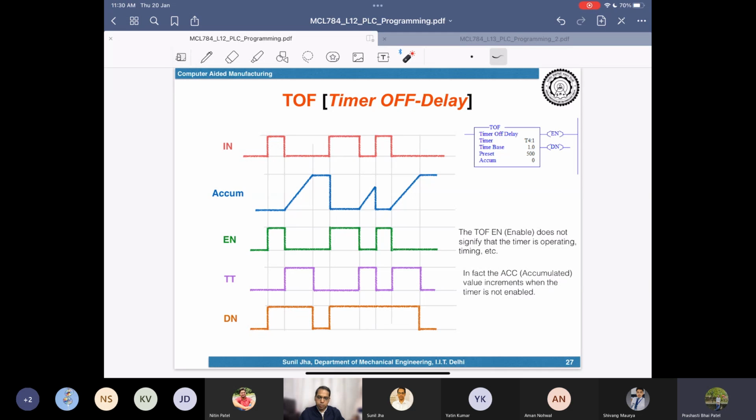It means that the output is immediately on. But your timer will not be starting, because I am not interested when you made the device on. I am interested whenever you remove the key. I'm interested whenever you make the input off in this case. So the moment you place the key in the key holder, input is true. You have some sensor inside that. And the moment I take out the key, at this point, I would like to count the time from now.